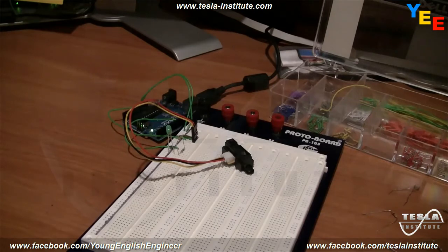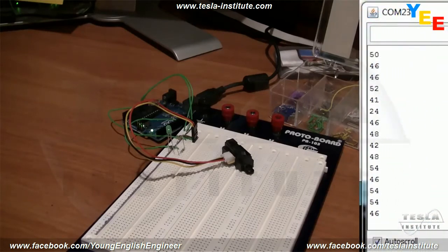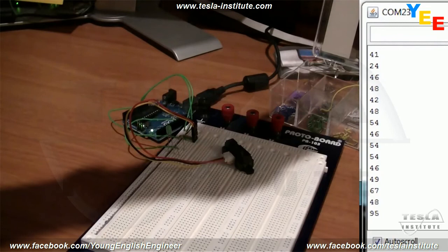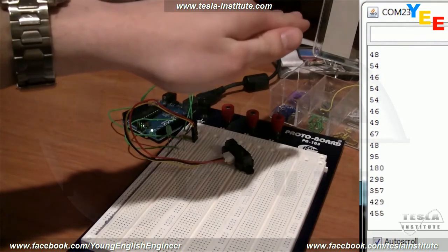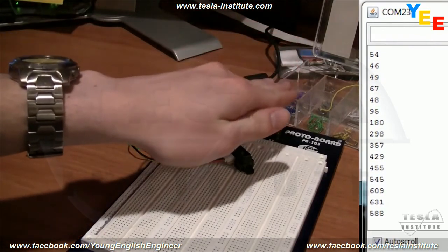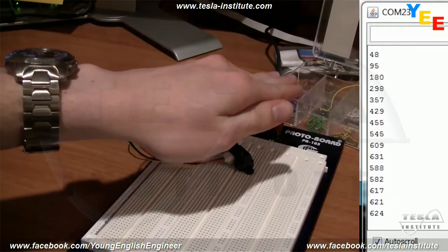You'll often notice that these kinds of sensors will give you a broader range because they've already designed it to operate on the whole 0 to 5 volt range. You can also buy these sensors in 3.3 volt iterations and other voltage versions. So if we look at the screen now, as I move my hand closer and closer, you can see that the value slowly increases from about 50 all the way up to about 600 something.